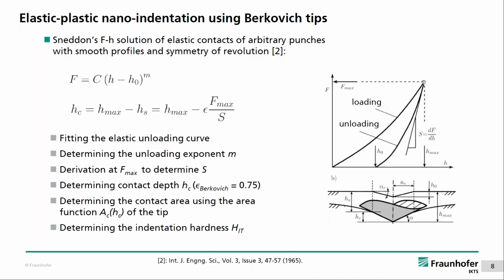So you load and there's plasticity, and you unload and it's fully elastic. And everything inside here, this hysteresis, is the plastic work. And once you've fitted this unloading curve with this formula, you are able to get the unloading stiffness at maximum force. And with this unloading stiffness, you can then calculate the contact depth.